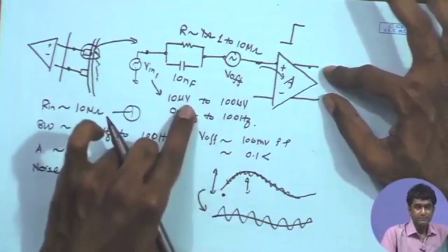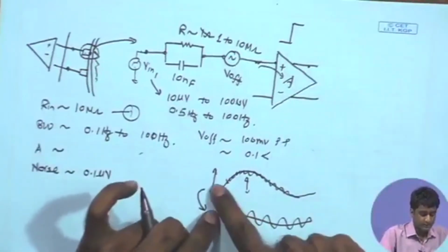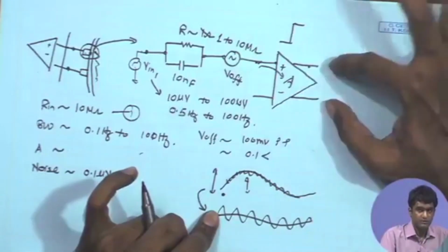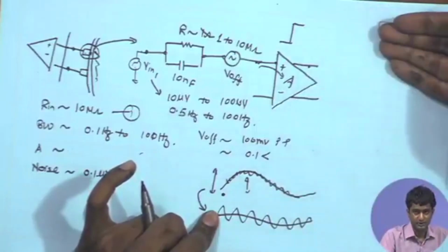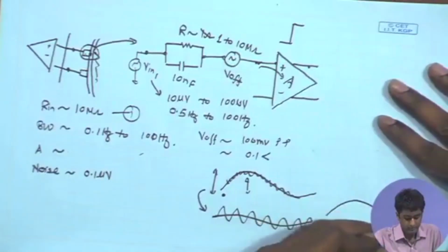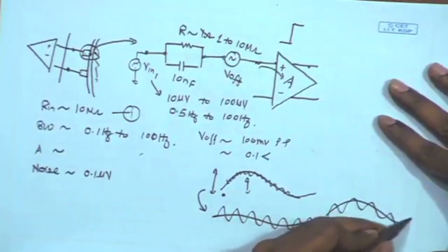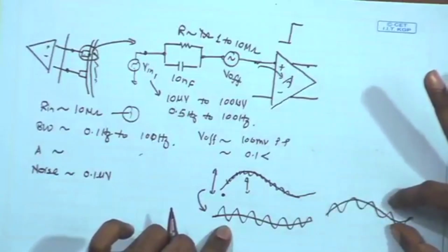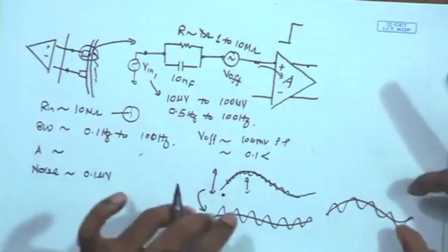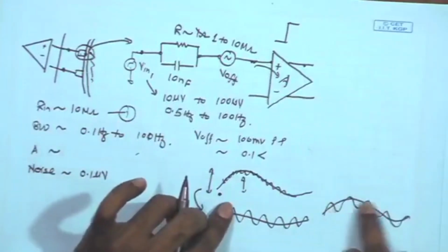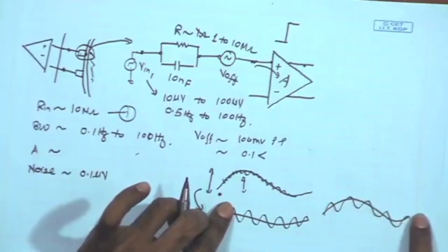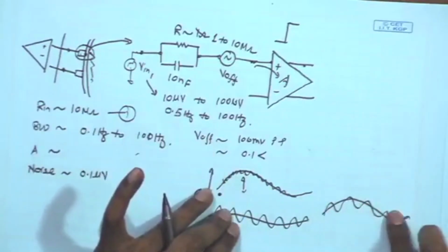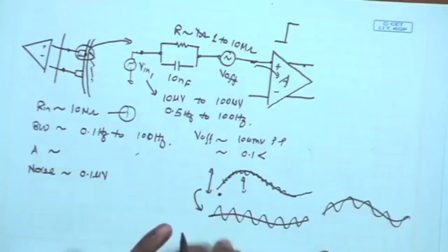But once again we are going to keep some room, because completely eliminating this strong slowly varying signal will not be feasible. There will be a remnant portion of it which can be comparable to the input signal or even larger than the input signal. It may happen that you still have a significant portion of the slowly varying signal, and on the top of that you have your desired signal. Therefore, we would like to keep some room or some margin for the undesired signal, and we will see why it is important. Using pen and paper we can try to come up with a design which is able to completely suppress this undesired signal also. That is feasible, at least in simulations, on paper, on calculation, it is possible to completely suppress this as compared to the desired signal.